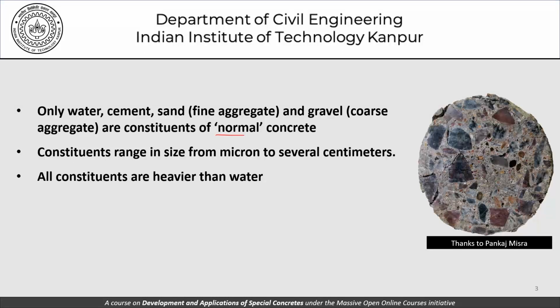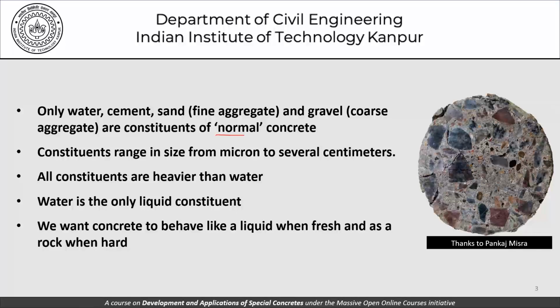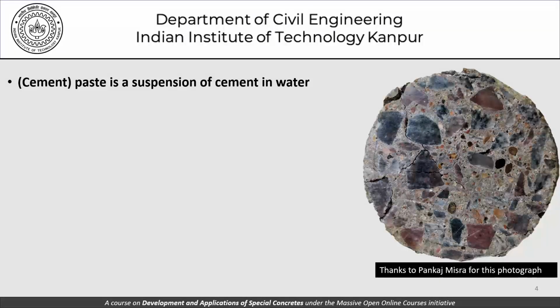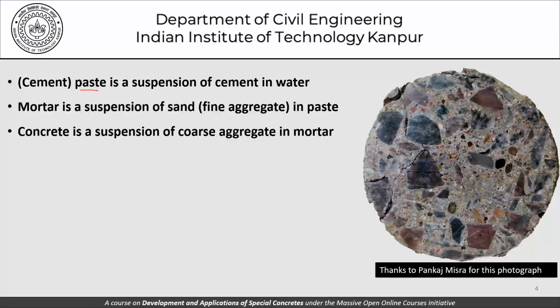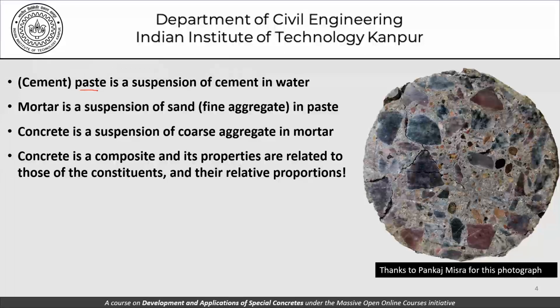All constituents are heavier than water. That's something which we must keep in mind. Water is the only liquid constituent, and that's the only thing that really contributes to or brings about workability, the flowability part of concrete. We want concrete to behave like a liquid when fresh and as a rock when hard. And we had said that, as far as the basic model is concerned, we'll talk of cement paste as a suspension of cement in water, mortar as a suspension of sand in paste, and concrete as a suspension of coarse aggregate in mortar.